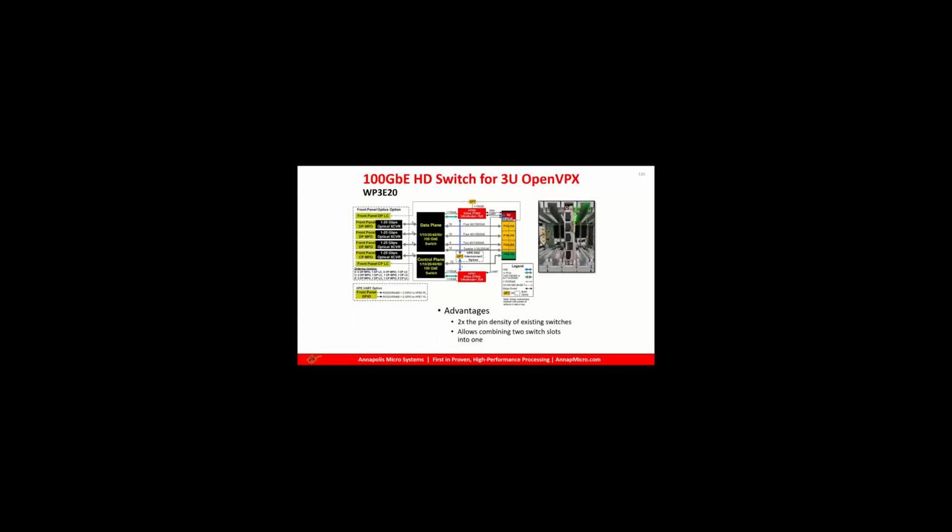So this is showing the Ethernet switch that can plug into an Ethernet slot. It actually has 2 separate chips, one for the data plane, one for the control plane, so that you have separation between those planes for those who want that. And there are 2 Zynq FPGAs as processors to control those switches. You could also maybe put some encryption in those or things like that if you want connectivity between.